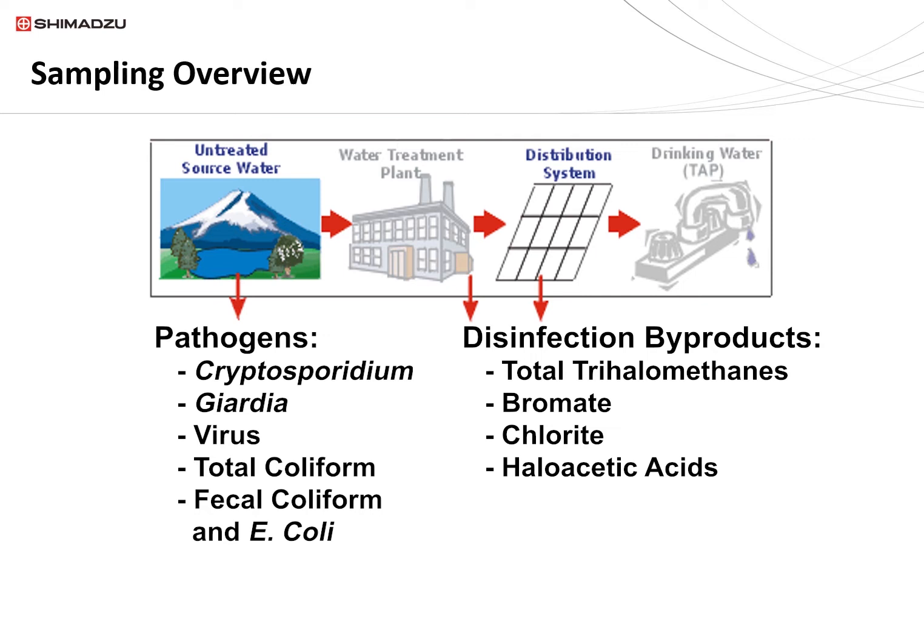The water is treated with chlorinated products, and the products produced are disinfectant byproducts such as trihalomethanes, haloacetic acids, bromate, and chlorite. The treated water is sent to distribution systems for consumption. Because these halogenated compounds are so tied to the NOM and TOC, there will be a brief discussion on this.